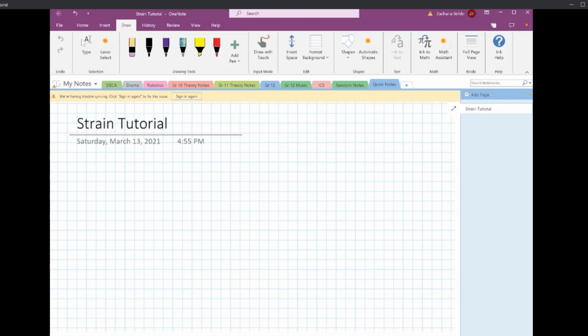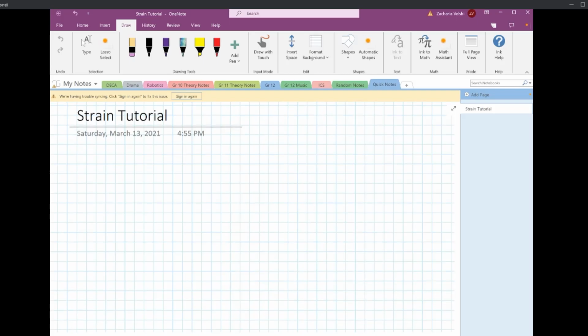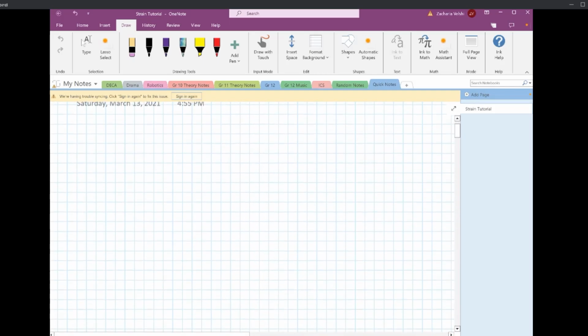Let's get started on strain gauges. First off, as a quick preface, strain gauges are a really useful tool for us on the team. We started developing with them, I want to say, two summers ago. They basically allow us to get forces and torques and essential information through our members, like all the car itself. So camber links and tie rods and axles, and we get all those little pieces of data that you use in your physics problems, which allows us to solve for different things on the car.